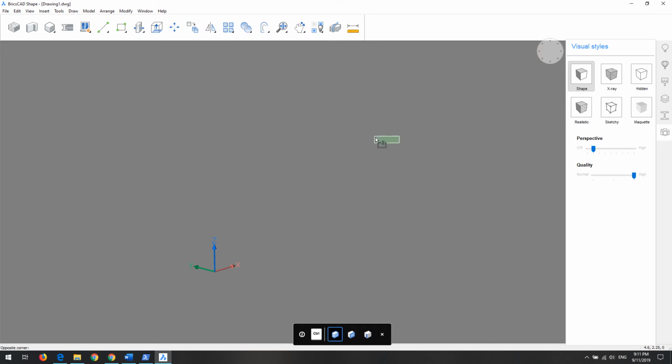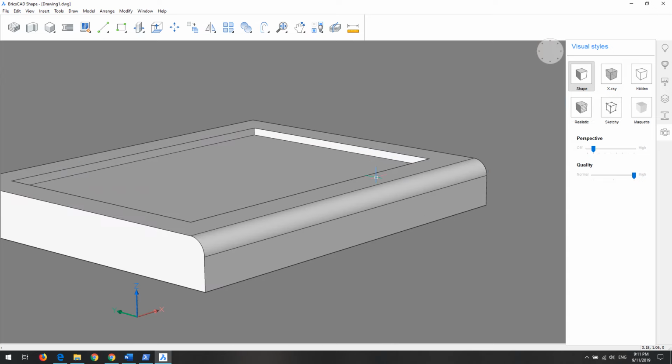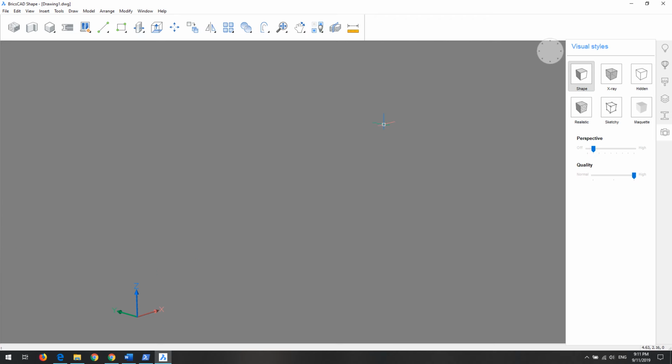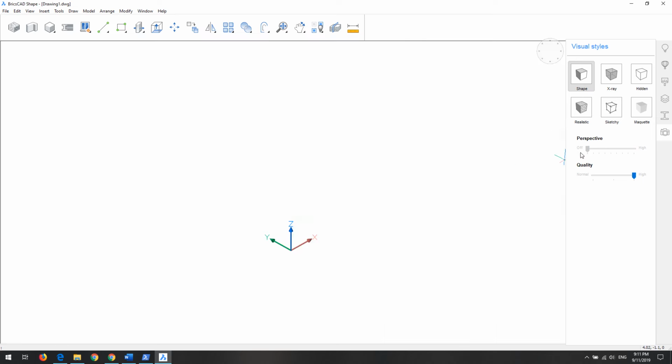It hides everything, including, let's undo that. But we just want to select maybe this portion, only the solid body, not the original polyline, and go to hide entities. Let's look from the top, and it's not easy to see.